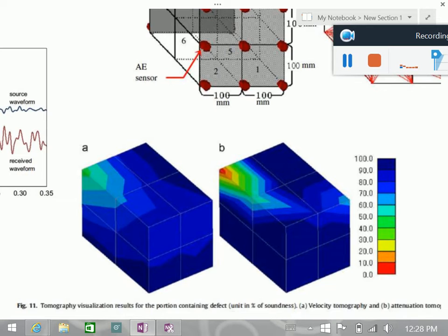Something like that. And you have to know that, generally speaking, attenuation is more sensitive. You have read the papers, the two papers. It's more sensitive to cracks and so on than velocity. So this is no surprise. Why won't we use attenuation then more often? Why do people stick to velocity? This is the question I want to close the class with, a discussion on that. If it is much better, as we can see and as you have read, why don't we use it more often?